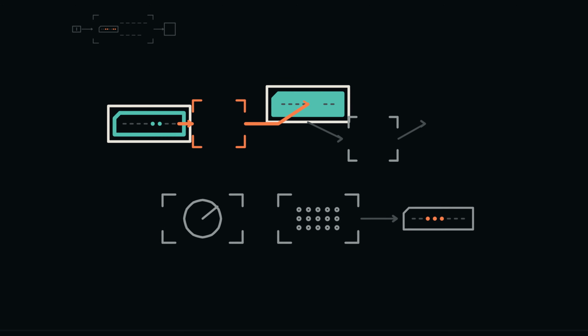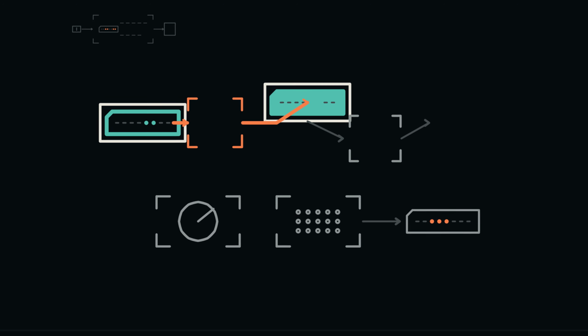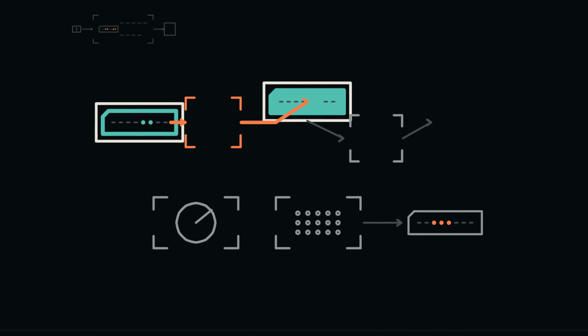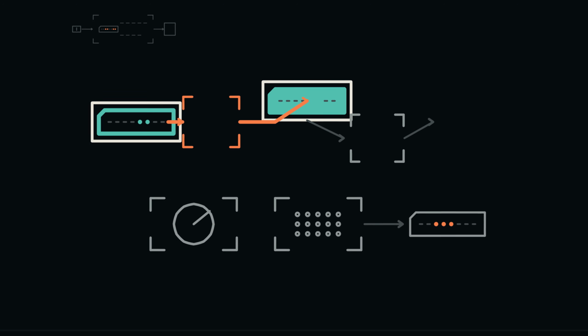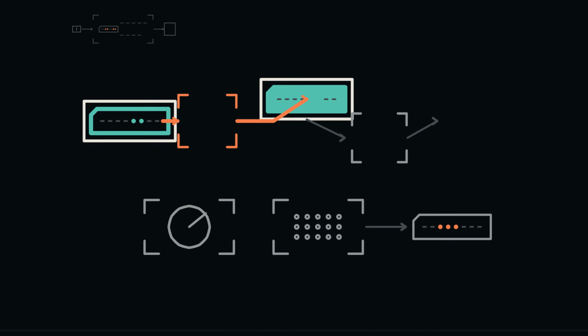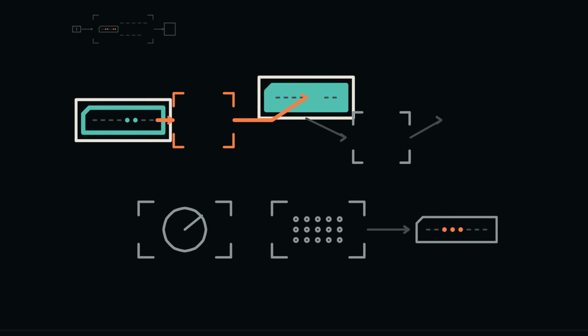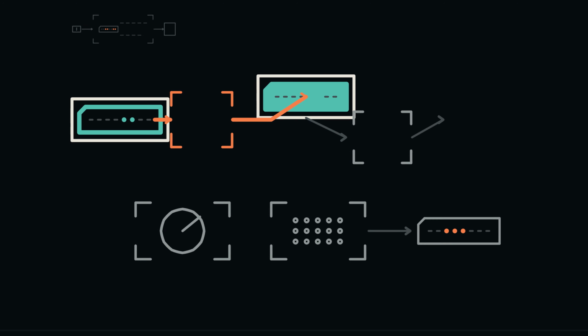An interrupt offers a different control flow contract. When an enabled device signal is accepted at a permitted boundary, the processor preserves enough information to resume the interrupted work and replaces its normal next instruction address with the address of a handler. The handler can inspect or service the device, then perform a defined return that restores the saved continuation.